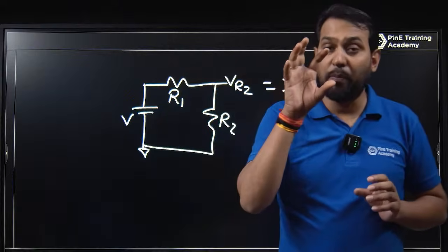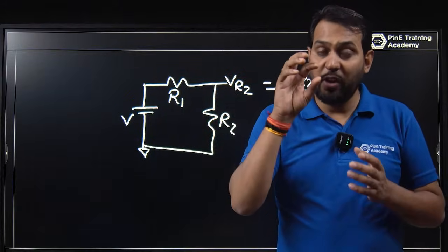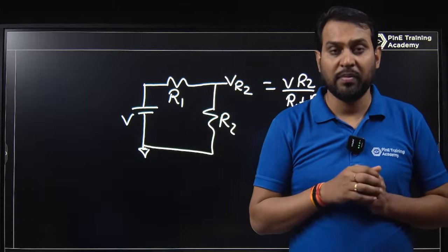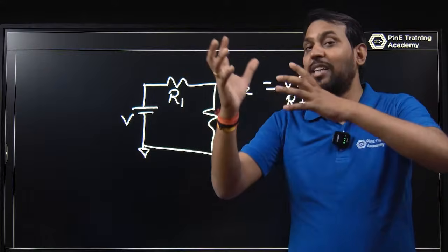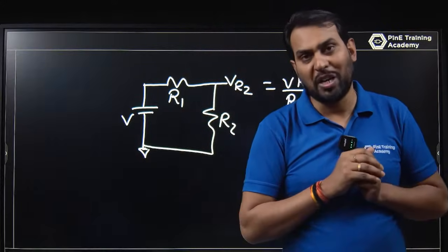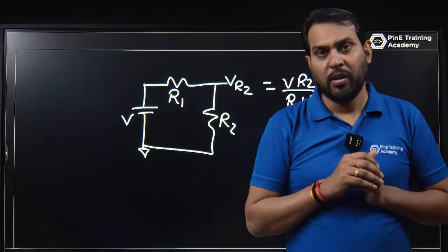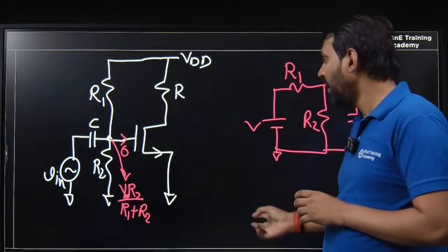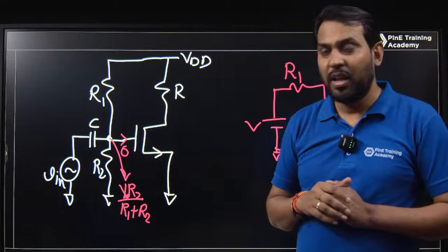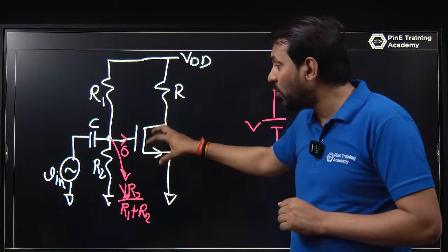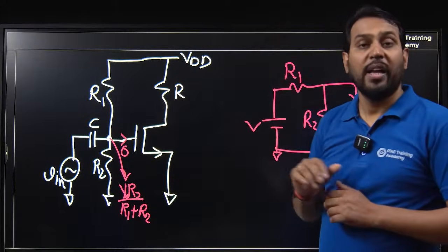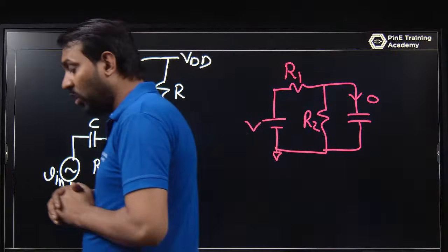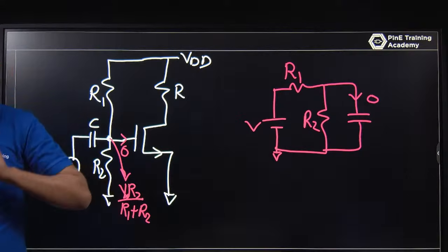If you want to look into this, you convert it into a small signal model, and then you can analyze that this is happening due to the MOSFET. MOSFET is just a symbol. If you are analyzing this MOSFET, you convert it into a small signal model and you find a dependent source. So the dependent source is the heart of the analog circuit.